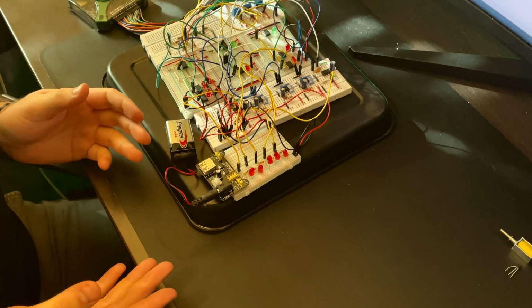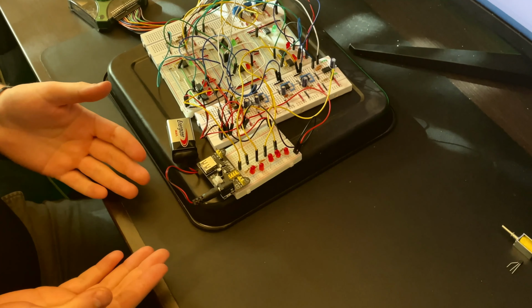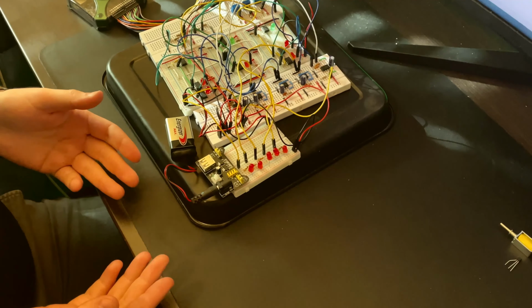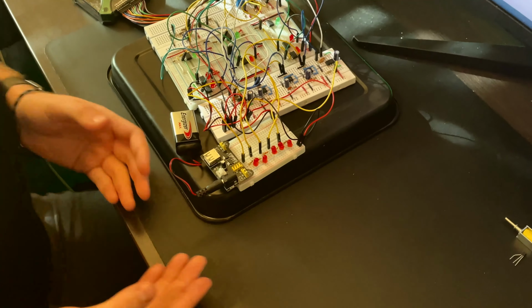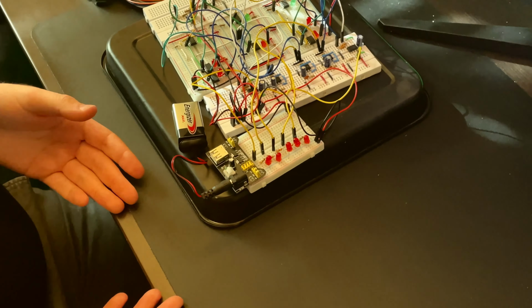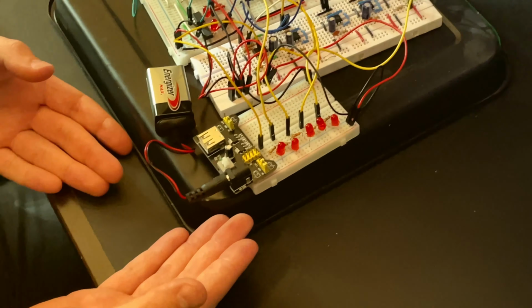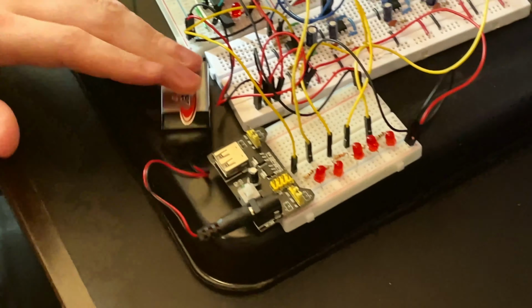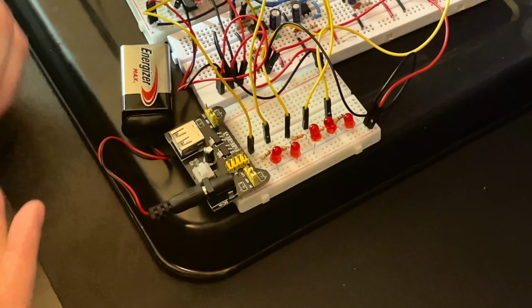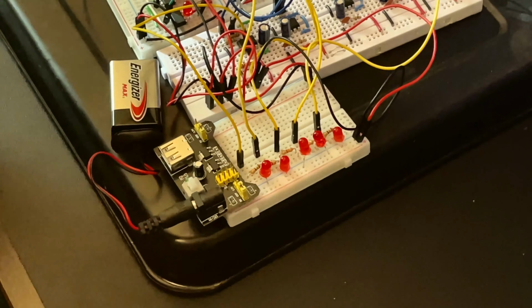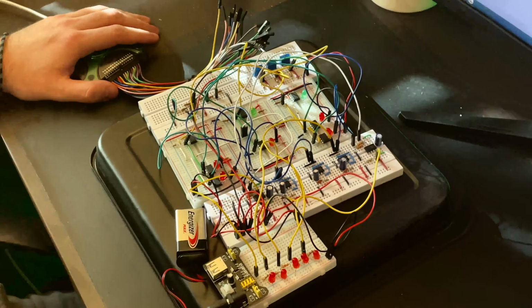Our third and final issue was power. We had already been running into power issues, and we're using 2 analog discoveries for the circuit in milestone 1. It became to the point where 2 was becoming not enough, so luckily we found this. It just takes a 9-volt DC battery and splits it out into some 5-volt supplies, and this gives us plenty of power, and we only need the analog discovery for our -5 volts.